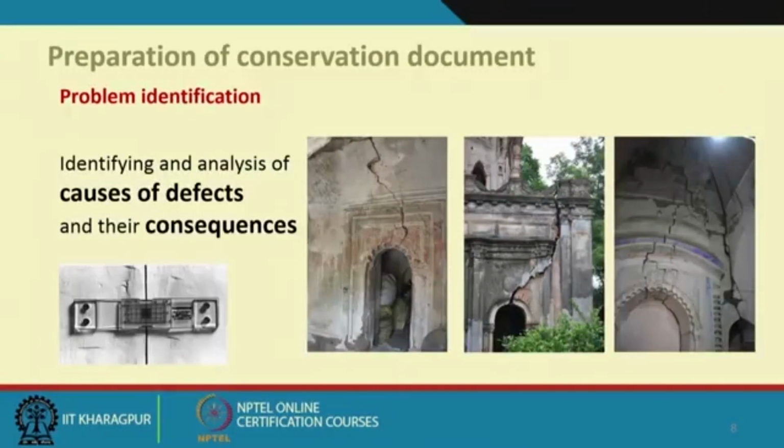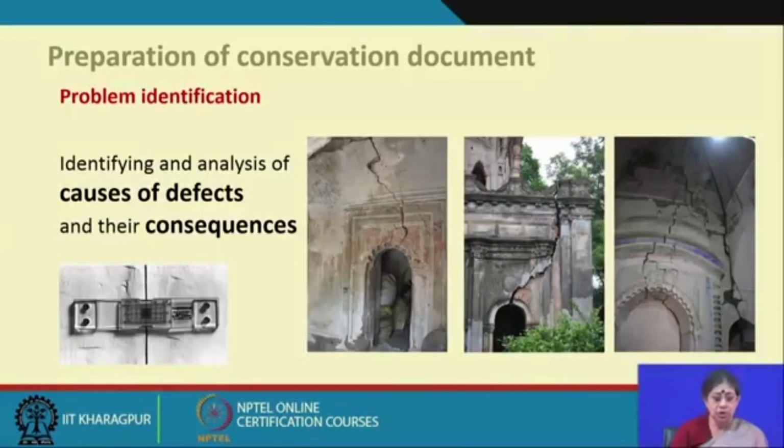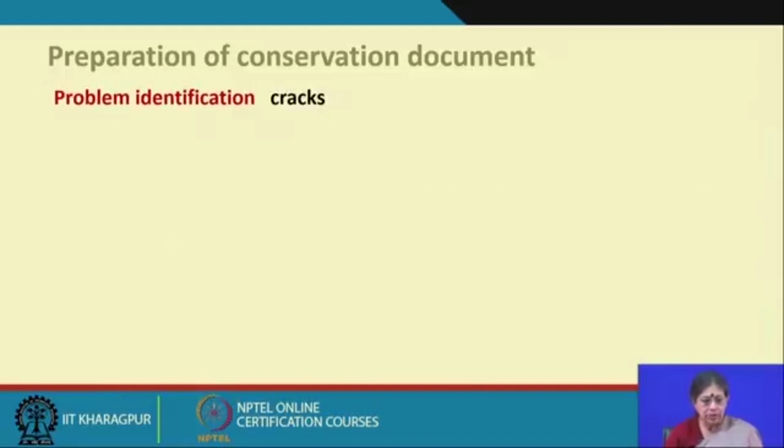There are different types of telltales, which is actually the monitoring of the cracks, which over a longer period of time can record the vertical and the horizontal displacement, where the crack is a live crack and a dead crack. And also simultaneously one has to use the other causes of decay and properly record what are the things we have found in that structure. That recording is very important.